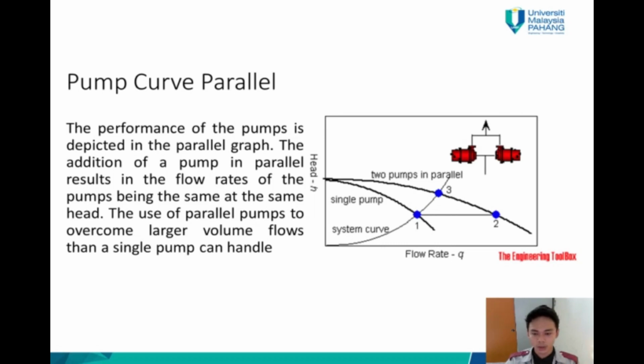This is a pump curve parallel. The performance of the pump is depicted in the parallel graph. The addition of a pump in parallel results in the flow rates of the pump being added at the same head. Parallel pumps are used to overcome larger volume flows than a single pump can handle.